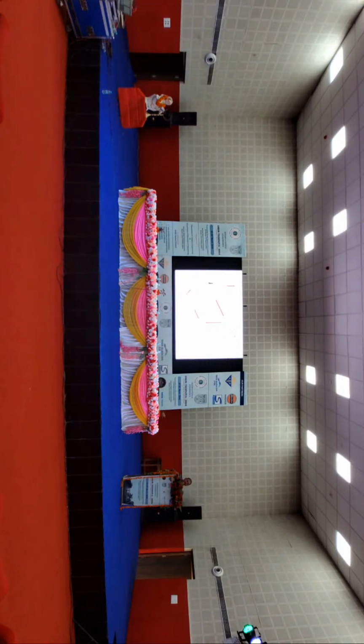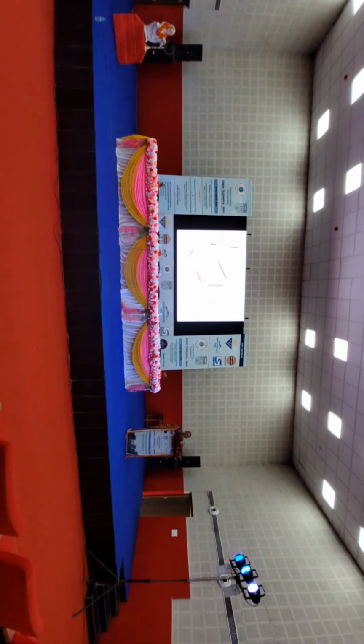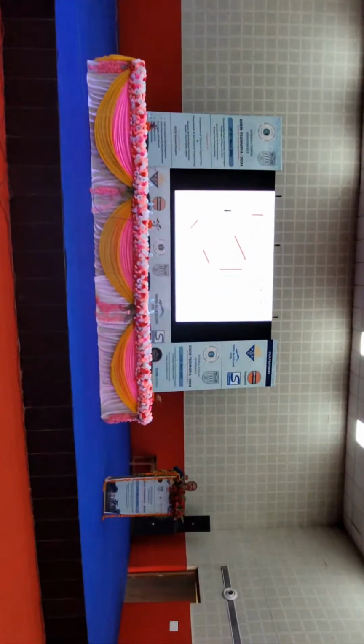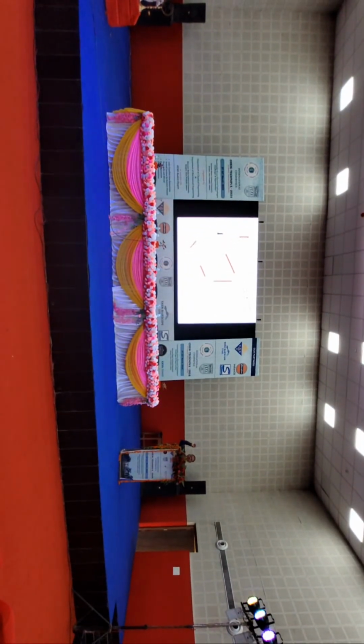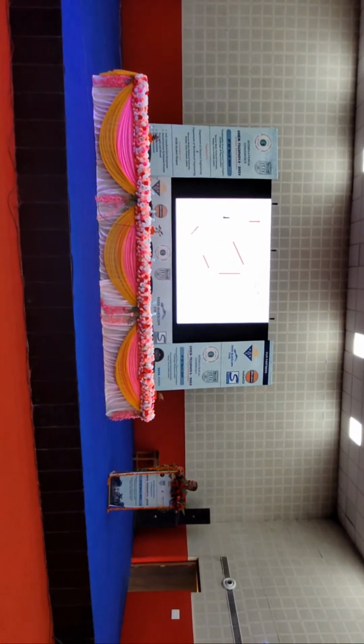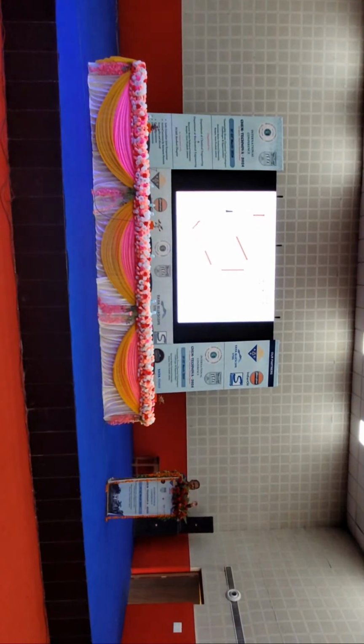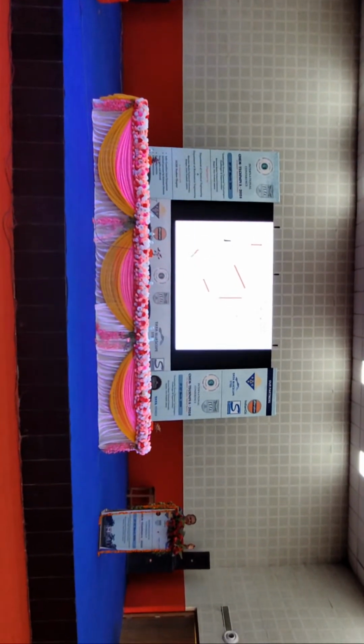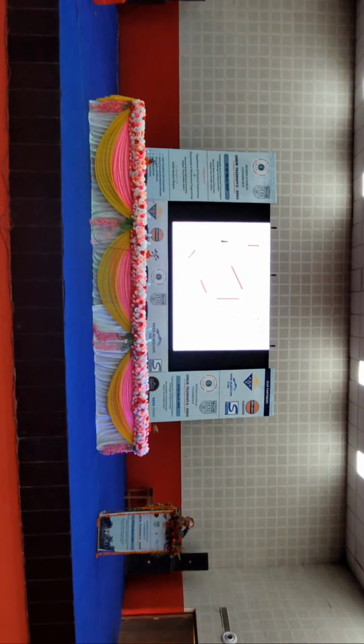So when I apply the non-isothermal ramp, 10 degrees centigrade per minute, from 30 to 300 degrees centigrade, you can clearly visualize when the resin curing gets initiated, when the peak curing is happening, and when the termination happens. So from the non-isothermal study, you will have the initiation point, peaking point and termination point.